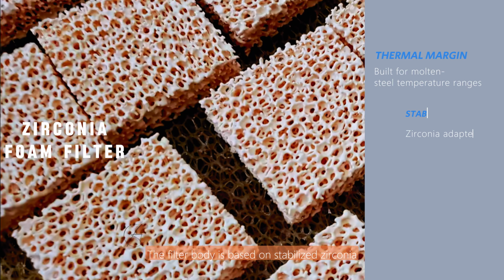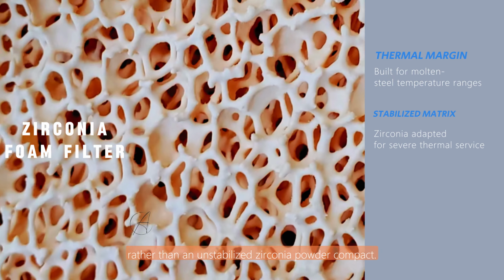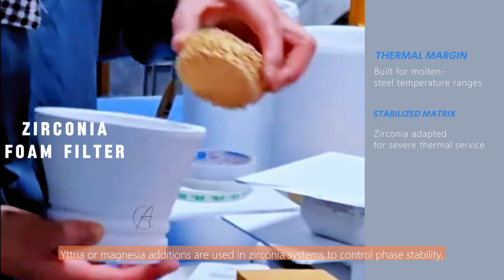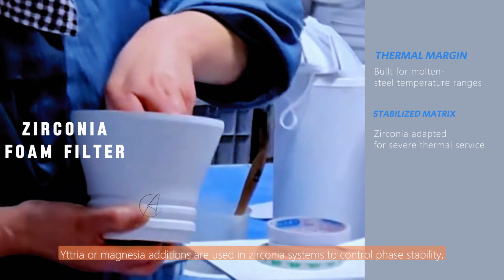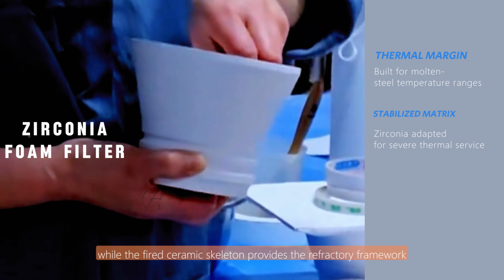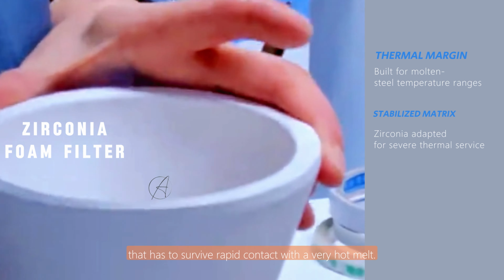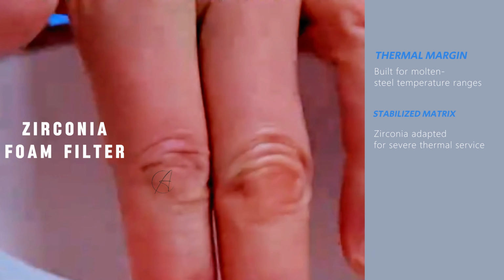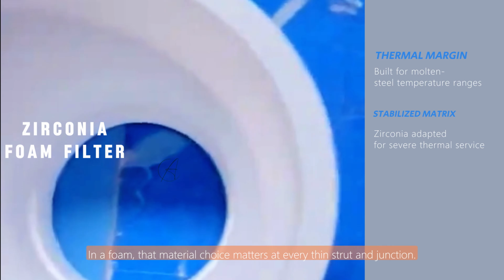The filter body is based on stabilized zirconia rather than an unstabilized zirconia powder compact. Yttria or magnesia additions are used in zirconia systems to control phase stability, while the fired ceramic skeleton provides the refractory framework that has to survive rapid contact with a very hot melt. In a foam, that material choice matters at every thin strut and junction.